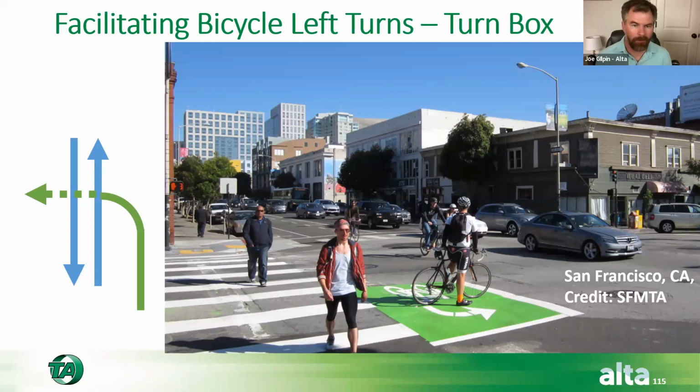So there's a lot of guidance on this in the interim approval that's out there from FHWA. NACTO has a lot of really great examples of how to use this type of device. And the key here is that you want it out of the way of through moving traffic. And so where this gentleman here is waiting, that can't be an area that is in conflict with any other moving traffic. And so it has to be sort of a sheltered area.